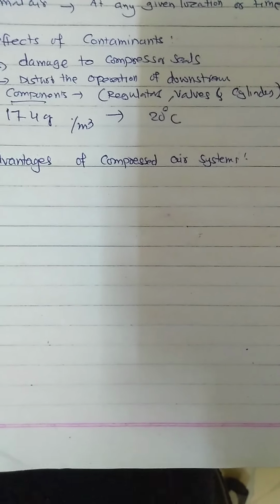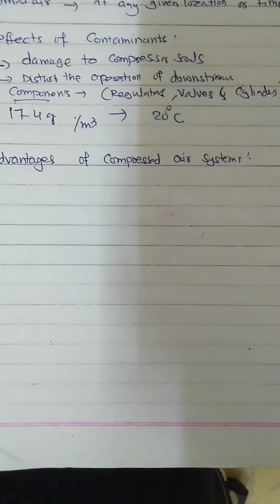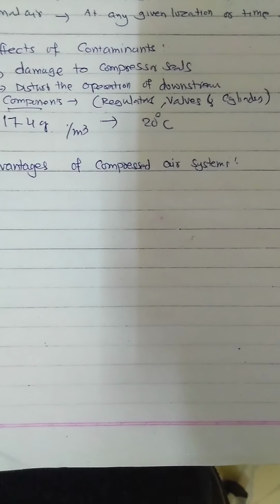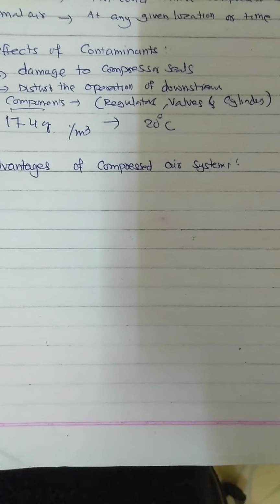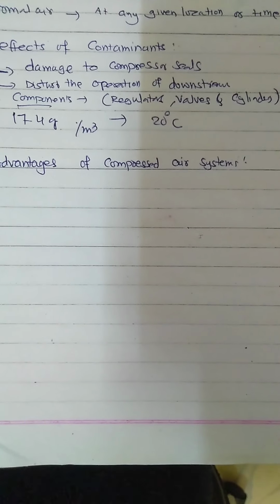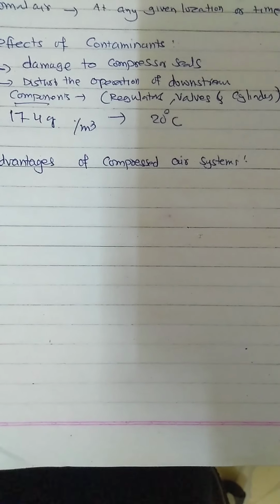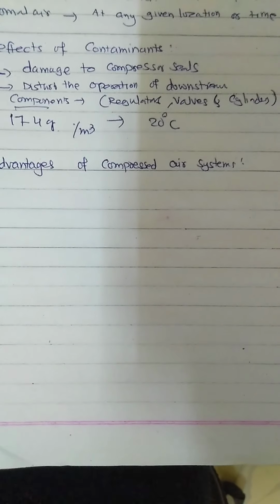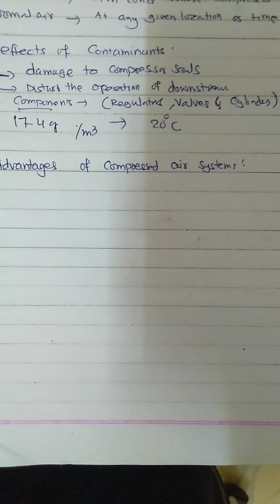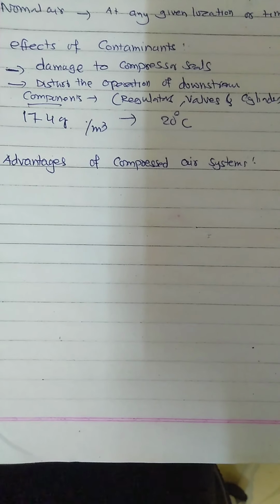If we talk about control, the actuator speed in a compressed air system can easily be controlled by the simple use of valves. There are different types of valves available. We will discuss that afterwards in another chapter. Because force can be easily controlled, mechanical elements driven by a compressed air system can be stalled for an infinite period without any damage. A compressed air system can quickly and efficiently be controlled with a few control elements and can readily be adapted for automation.